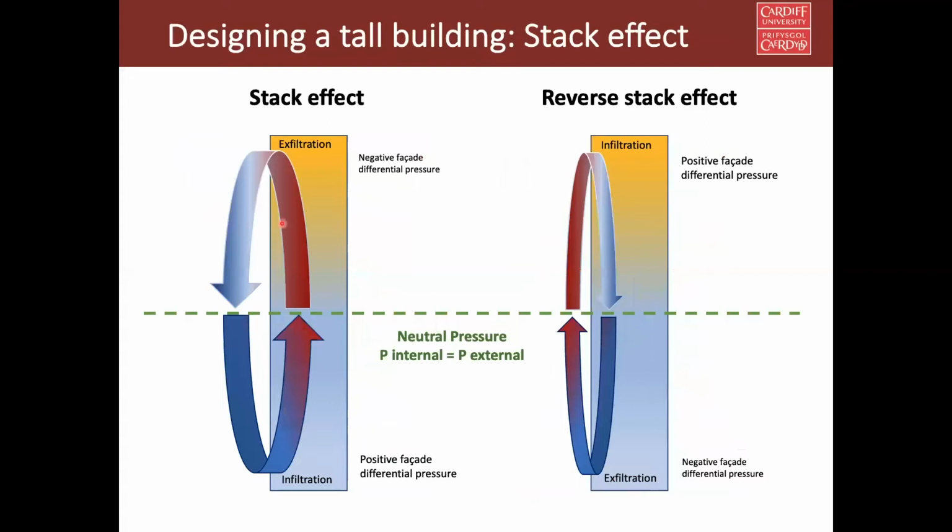So in the wintertime, you have this loop that is creating the stack effect. In the summertime, you have the other way around loop. So that is also a reverse effect. But you can see in my drawing that this is a thinner line, this is a thicker line, because in the wintertime, we have a higher delta T temperature difference. In winter, we have an internal temperature of, for example, 23 degrees Celsius, and outside temperature, let's say 0. So there is a 23 degrees Celsius temperature difference. But in the summertime, we again have internal temperature 23, but outer temperature maybe 30. So there is only a 7 degree difference. So there's not much differential. That's why the effect is a little bit lessened.